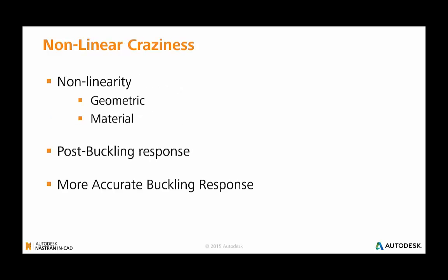A nonlinear analysis can be a bit more challenging to conduct. It's going to take into account both geometric and material nonlinearities, and we've talked about some of those in previous webinars, but it's also going to give you the post-buckling response. So what happens after the part buckles? What's the reaction of the geometry post-buckling?